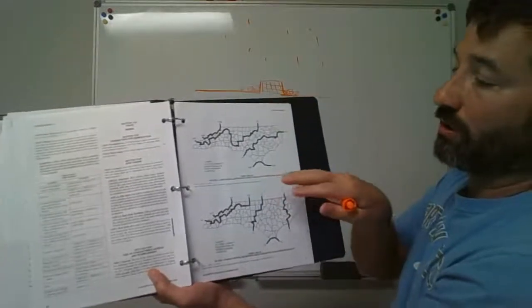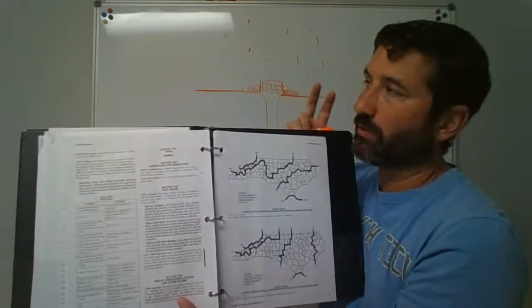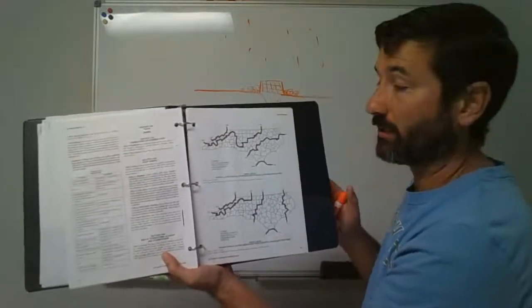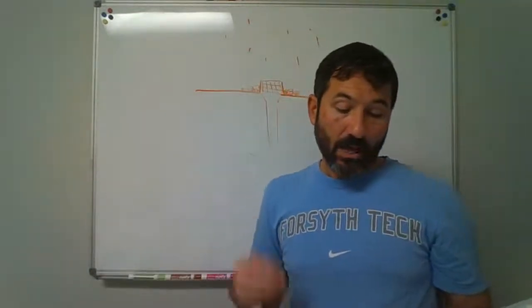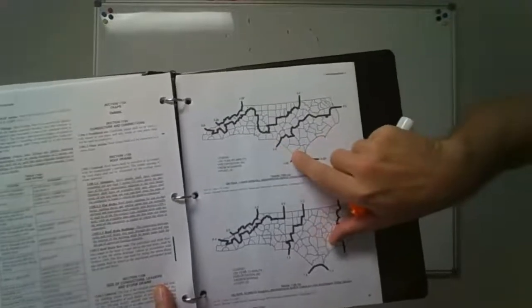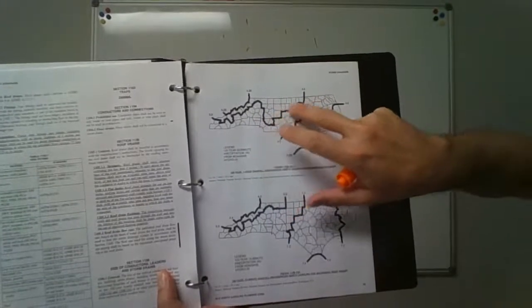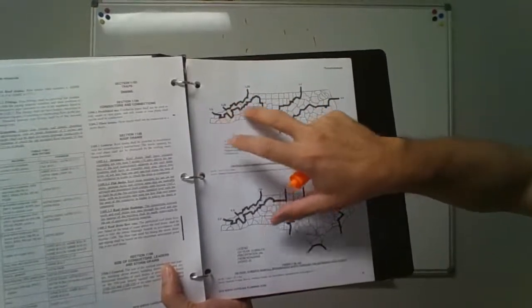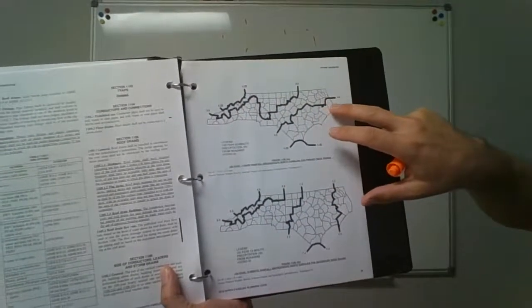Okay, they took the last 100 years that we've had, and they've looked and said, okay, what's the greatest amount of rain that we've had over a 1 hour rainfall? So it's settled in and rained for an hour. How much do we have in inches per hour? If you look at it, we're over here, okay? So we're following close to right along this 3.5 inch line, somewhere right in here. The mountains over here, we're looking at 3.5 to 3.25. If you go back down towards the coast, you're looking at closer to 4.